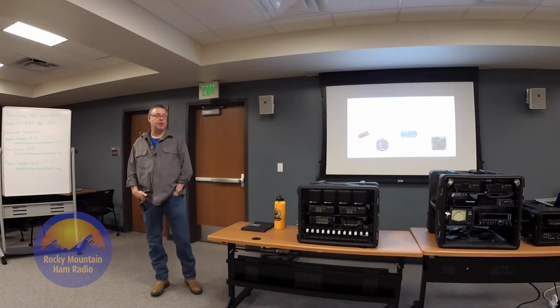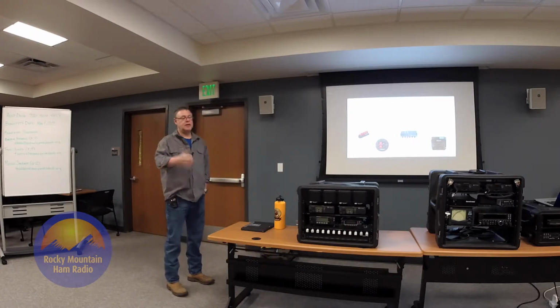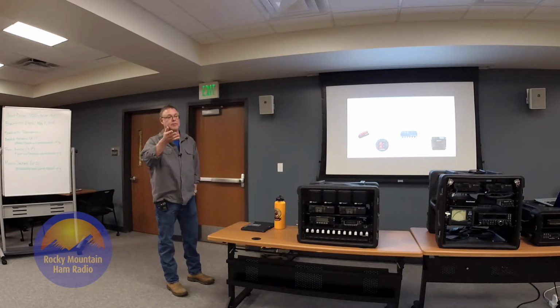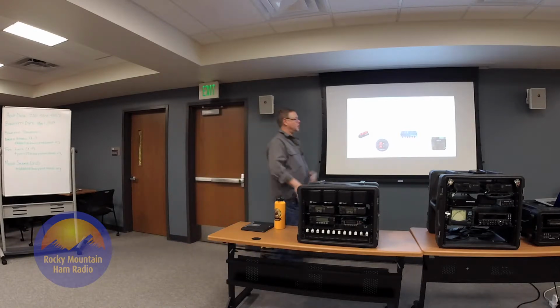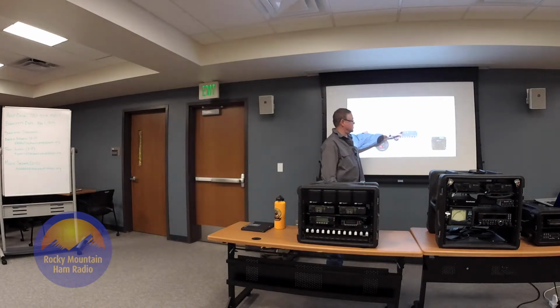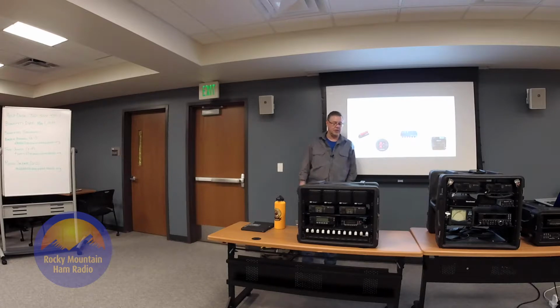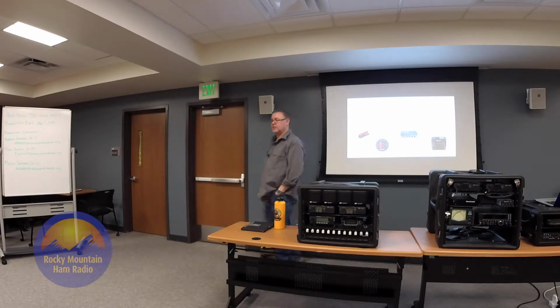All the rig runners I use now have that feature on just about every one of them that I'm aware of, whether they're 20 amp or 80 amp. I'm pretty sure they have it on all of them. The LED is actually inside the slot on the circuit board, but it shines through. There's no problem telling you have a blown fuse on that slot.